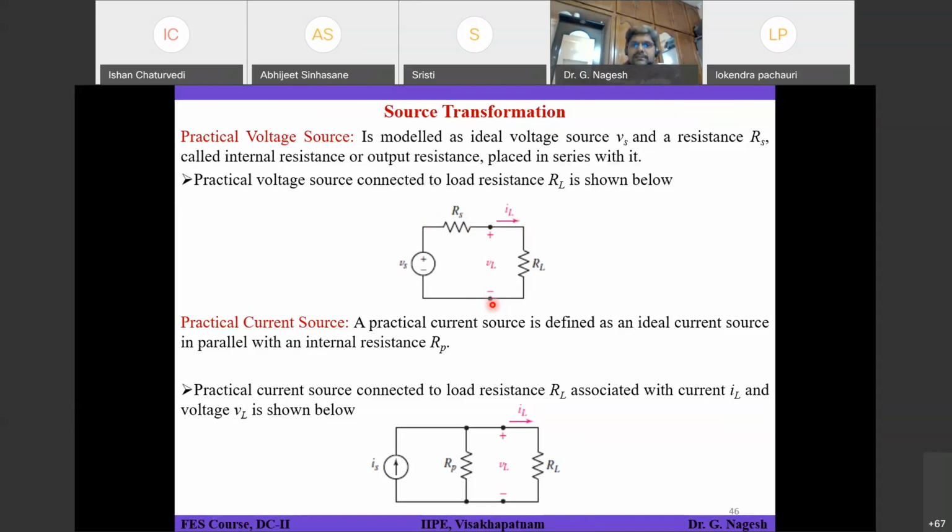Okay, so that circuit voltage which is actually coming to the circuit will keep on reducing with increase in the current. What it indirectly means is I am a practical voltage source, so my voltage is not going to remain constant. Based on your current drawing, I am going to drop my voltage level. If I increase the current level, my voltage is going to drop.